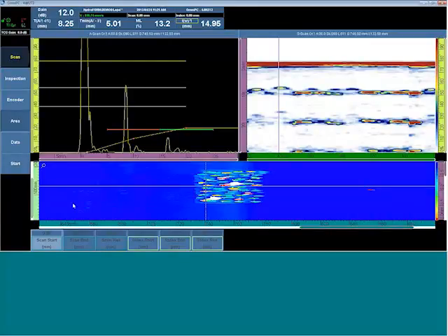So we would build the C-scan one part at a time, one stroke at a time, continuously. The software will not allow you to configure a C-scan that exceeds the capacity of the instrument to save the data file. For most MX2s, that's 300 megabytes. For most MX2 first generation OmniScan, that was 160 megabytes.